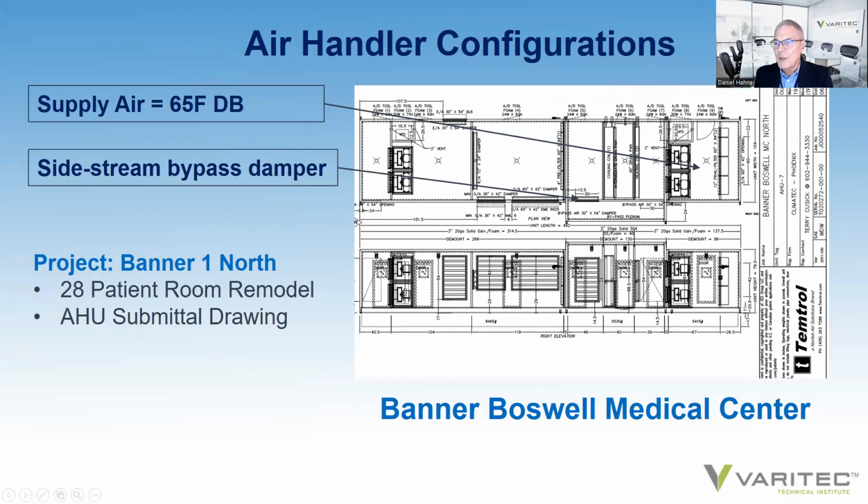Here's an example of the air handler we laid out for a customer at the Banner Boswell campus, where a side plenum was added to circumvent the cooling coil. Here's your modulating damper. Your discharge air temperature sensor would be placed on the discharge of the unit, and this damper modulates open and close to maintain 65 degrees when your dehumidified air is provided off the cooling coil.